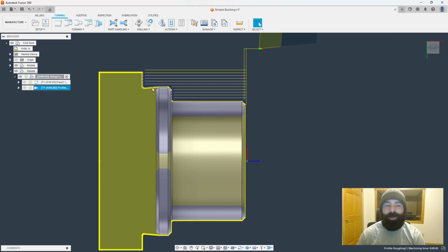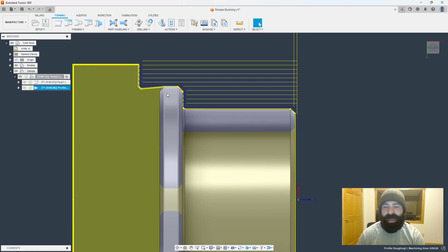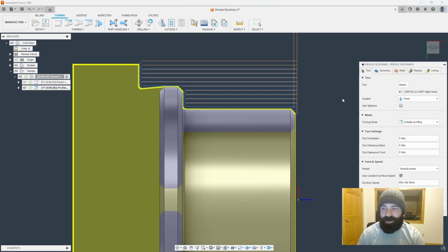So what you're going to notice happen now is we are going 200 past the back of our part, but we are doing what I like to call waterfalling or undercutting. And this is, again, one of those things that we can determine what's happening and how we can adjust that. So in this case, we want to modify not where the blue lines are in a containment of X and Z. We want to modify how the blue lines are acting.